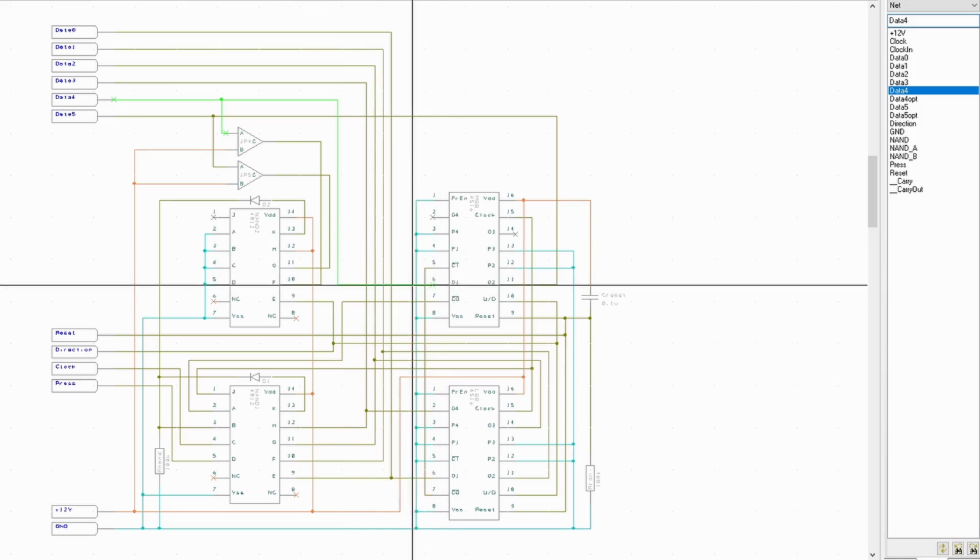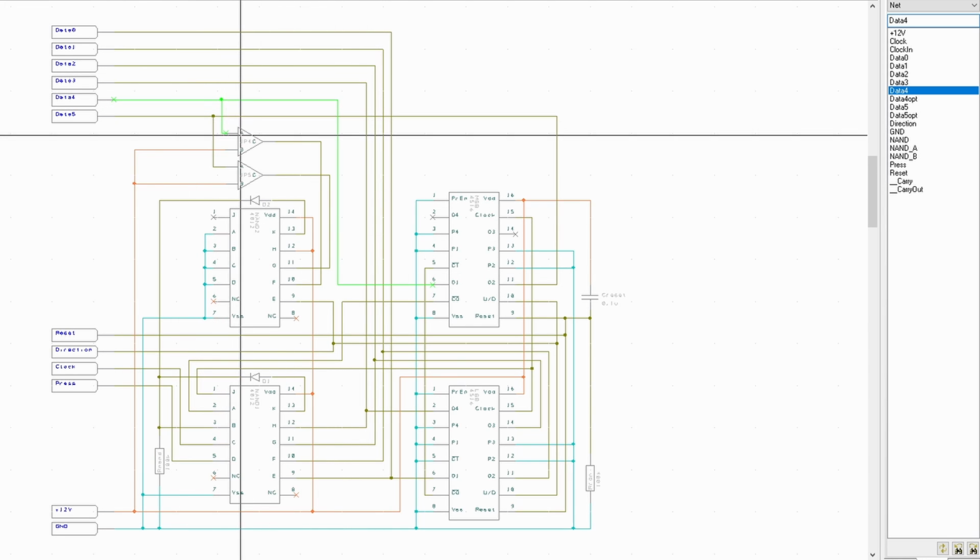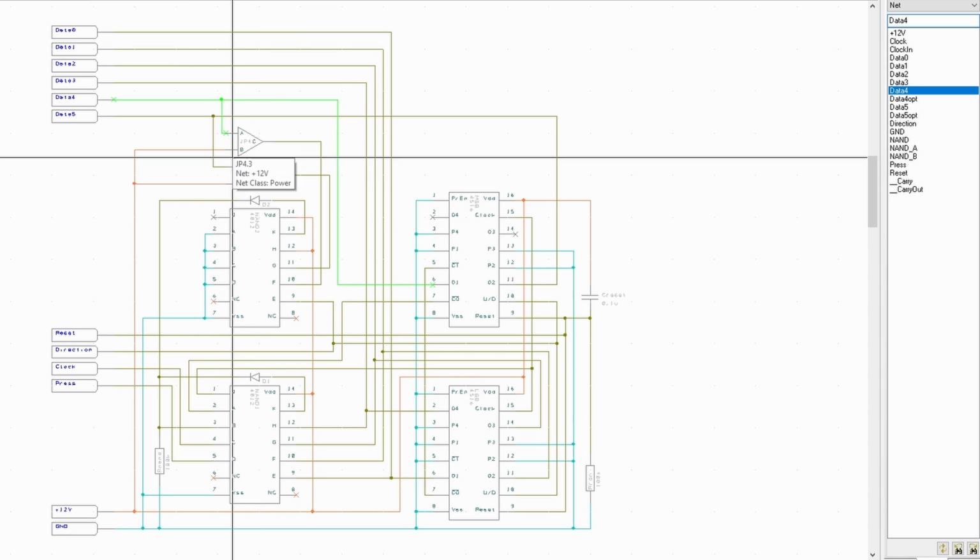But remember, the reason I need to make sure it impacts our logic is because if we're using 16 shades, I need the counters to stop when it gets to the maximum intensity, 16. But if I'm using 32, I don't want the counters to stop at 16. I want them to stop at 32. So I need to change my logic a little bit. And so this data 4 line that comes out of the counter, it does go to the output, but it also gets fed into one of these counters as an input, but it's an option. And that's what this triangle is.